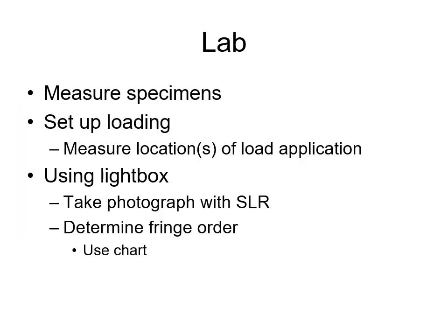So this leads us into the actual lab that you're going to be doing next week. Within this lab, you're going to need to measure specimens, set up the loading, measure the locations of these load applications, use the light box in order to take pictures with the SLR, and you can use that chart that we just took a look at in order to determine the fringe order.